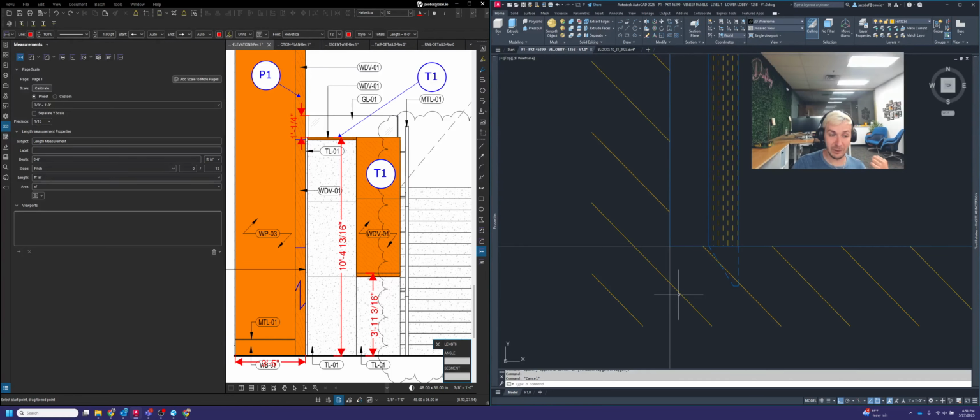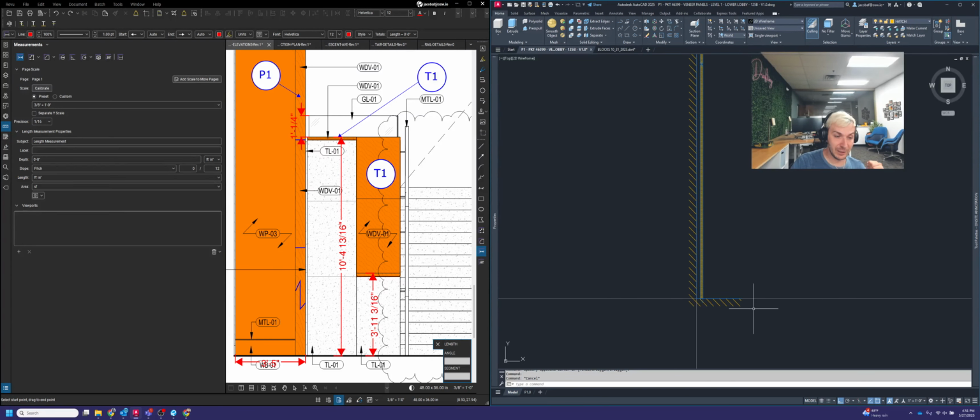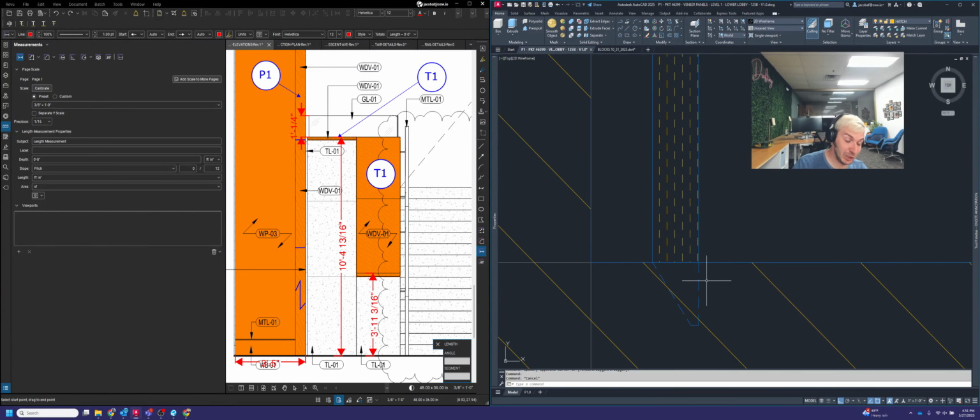So scribe has a really important purpose out in the field for that reason. It helps keep everything flush and level. If you don't have that scribe there, the other problem that you might see, again, kind of hinting at that, is that you may see a gap at the floor where the floor starts to go down or up. You may start to see a gap or it may just look not incorrect. Like you'll see a tiny gap between the floor and the bottom of that panel. So it's really important to show scribe whenever you have something touching the floor like this.